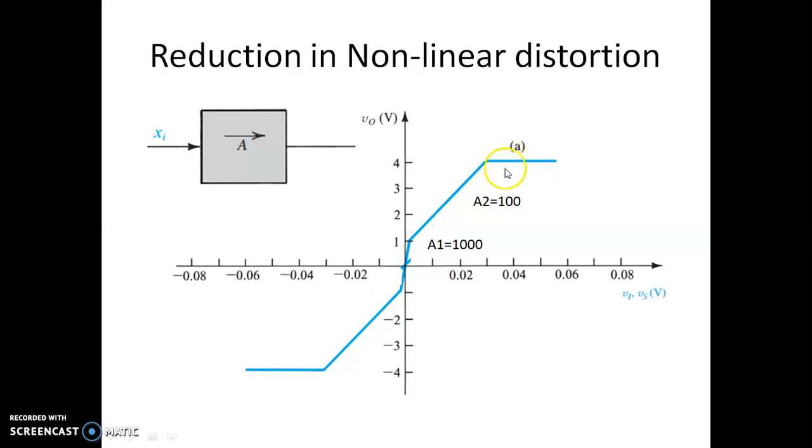The output is almost equal to input. Okay, this is not having any gain here. So what I want to say is, for lesser amplitudes, the same amplifier has more gain. As the amplitude of the input signal increases, the gain keeps on changing. So this is the non-linearity of an amplifier. This property is exhibited because the amplifier has a transistor, which is a non-linear element, as an active element in that entire circuit. So this non-linearity over the input voltage has to be reduced.